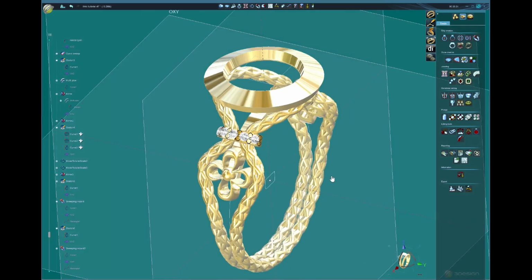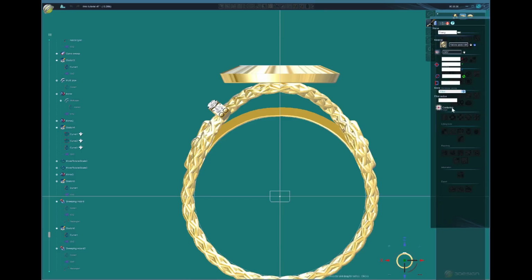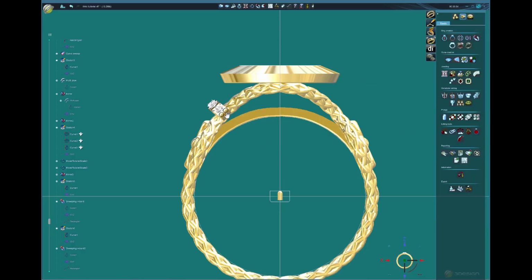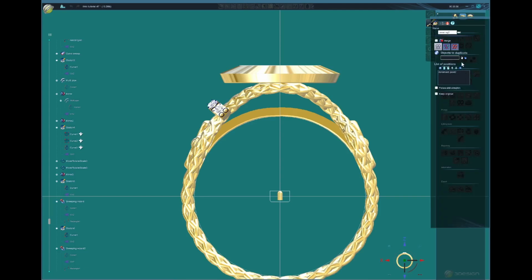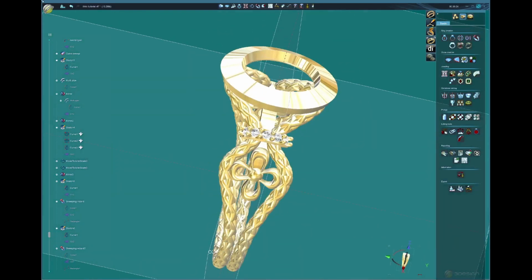Nice. And we're going to make the prongs also for that specific part, because we want 0.5 millimeters, one rounded, and we're gonna go down minus 0.4. We get the pavé, jeweling, duplicate the prong. Perfect. The height that I want, very nice. The setter is gonna be very happy.